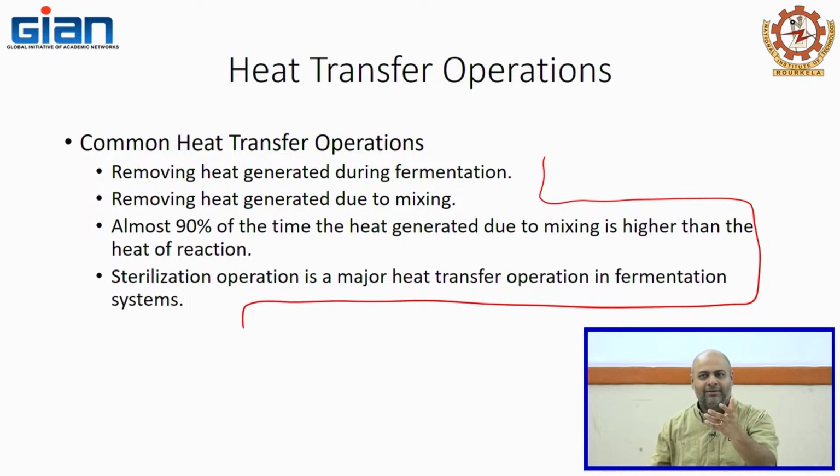You remember that? You have to take that into account. If the heat is being provided just from the outside surface of the fermenter, it would be conduction. But if the fluid is moving over the surface, it is conduction at the interface, but there is a flow of the fluid, so convection has to be taken into account.